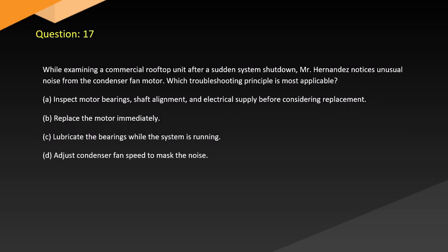Question 17. While examining a commercial rooftop unit after sudden system shutdown, Mr. Hernandez notices unusual noise from the condenser fan motor. Which troubleshooting principle is most applicable? A. Inspect motor bearings, shaft alignment, and electrical supply before considering replacement. B. Replace the motor immediately. C. Lubricate the bearings while the system is running. D. Adjust condenser fan speed to mask the noise.